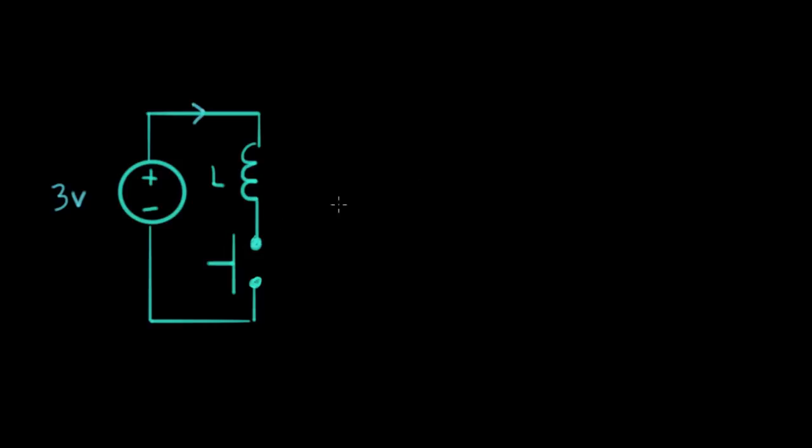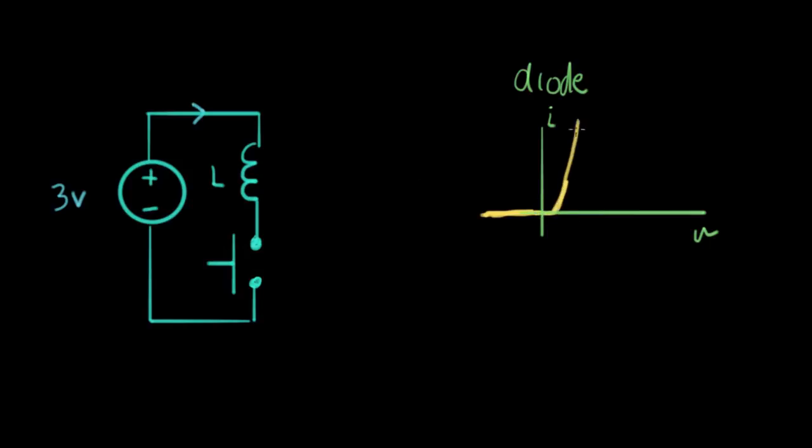The best way to solve this is with a device called a diode. And this is another semiconductor device. It's not a switch, but a diode has an IV curve. Here's V, here's I, and it looks like this. I'm just going to sketch this. The current is 0 when the voltage on the diode is negative. And somewhere around here, the current goes up like that.